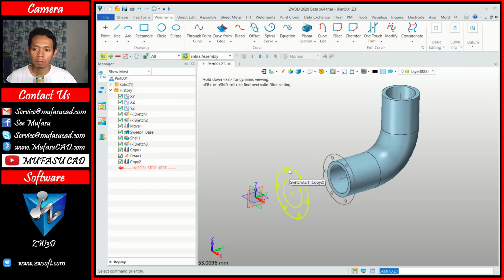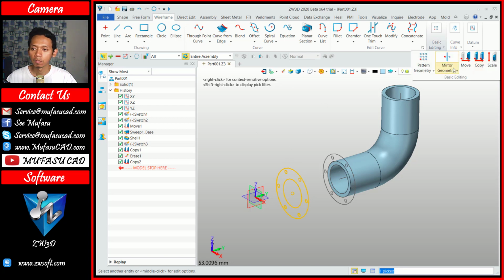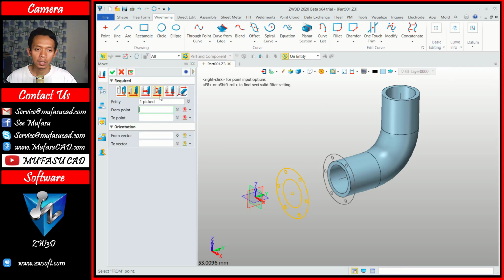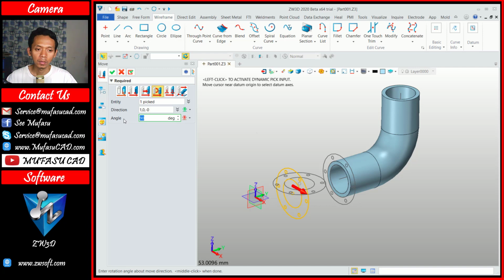Now we can use the move command to rotate this sketch. Okay, I will use the move command. And we click this rotate option, rotate entities. Okay, I will set the direction to the right axis. Okay, you can click here for the right axis. And then we rotate with an angle of 90 degrees. You can click OK to apply.